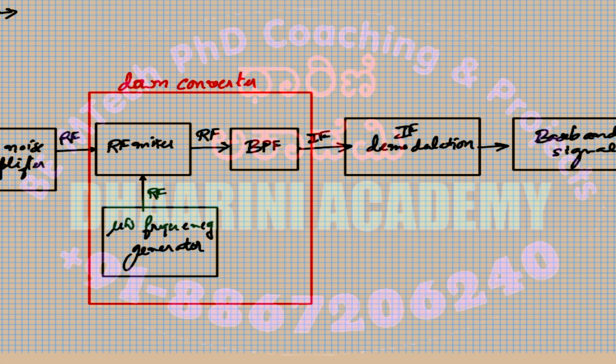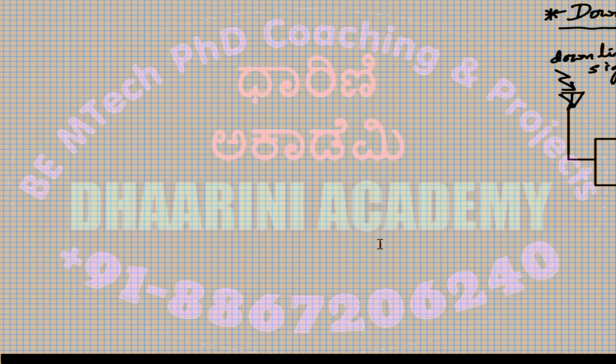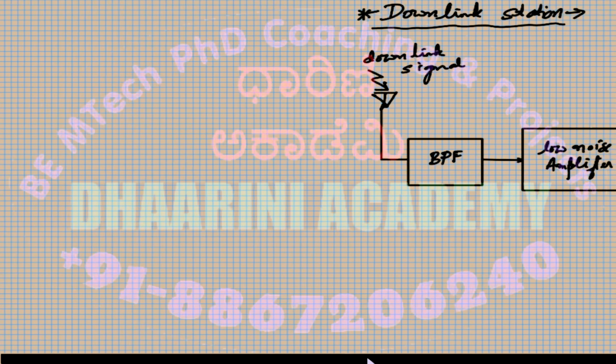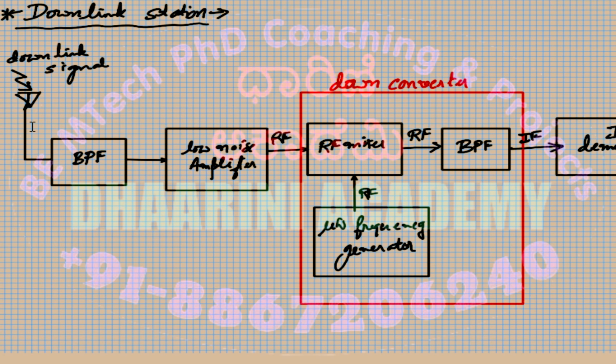I'll just show you where it's going to happen. In this circuit you are supposed to add, as soon as you receive something, this. The BPF will come later. Before that, I'll make the modification. Whatever signal I receive, I correct that. I'm going to perform the Doppler correction with two components: one is a Doppler extractor, and the second component is telemetry recovery.